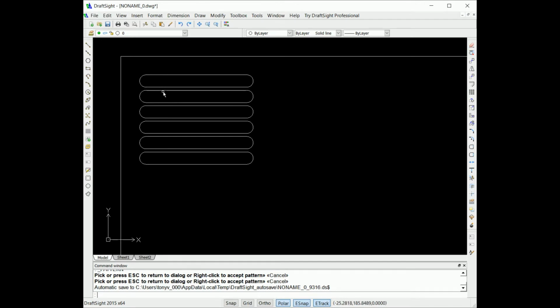So this distance between here is 1/8 of an inch, and as you can see, you couldn't get your hand in there, and large objects couldn't get in there with the fan blowing in there. It might pick up something in the air and blow it in there or suck it in there, and those would prevent anything large from going into the box or whatever it is that you're designing. Sometimes you put a foam filter in front of the fan, so that it keeps a lot of the dust from going in there as well.